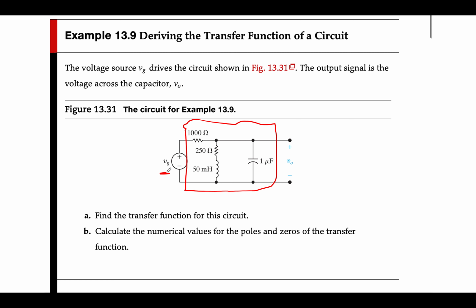So by definition, we've got to have a situation where this has been drained of any energy. Otherwise, when we do the Laplace transform into the Laplace domain, we would introduce sources here because of the initial conditions, and we couldn't find a transfer function. So always when finding a transfer function, initial values are zero.